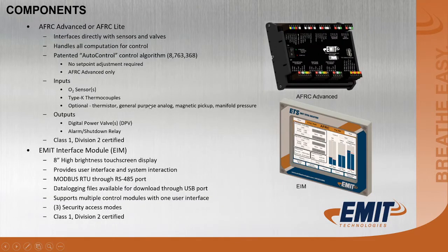Now the differences in the air-fuel ratio controllers: the AFRC Advanced or the AFRC LITE interfaces directly with sensors and the valves, so the oxygen sensors, the thermocouples, and the digital power valves. It handles all computation for control. In other words, you don't have to choose a set point with the AFRC Advanced. You have the option to use it as a set point control, or you can use it as an auto control mode.